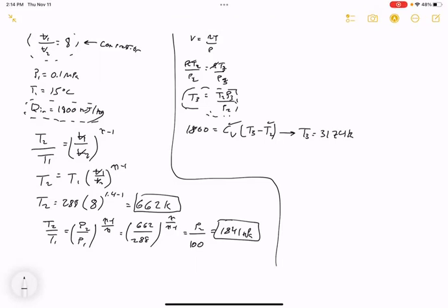So if I want to now find the pressure, can I use the isentropic relations? No, because the isentropic relations, as the name would imply, are for isentropic processes. And we know, or you'll learn in class, that an isentropic process cannot have heat addition or rejection. So since we're adding heat, this is exactly what this step is. We can't call this an isentropic process.